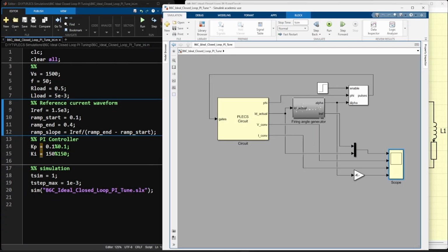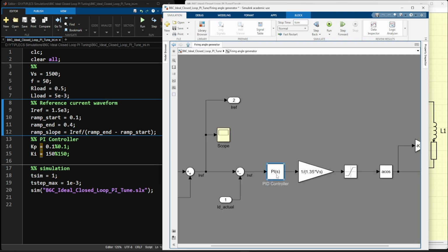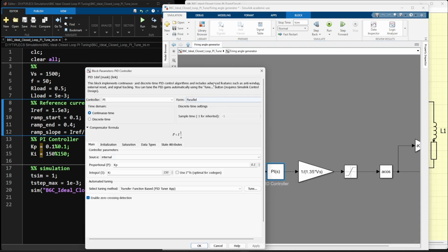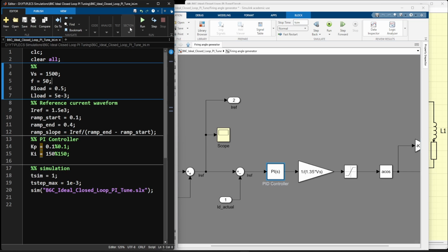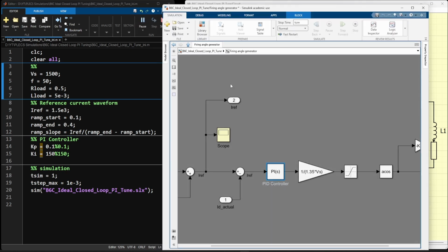Now the motto here is to change these values. These are automatically generated or calculated values from Simulink. So I will simply replace these values with 1 and see the response of the controller. Let's run it once and see the effect.